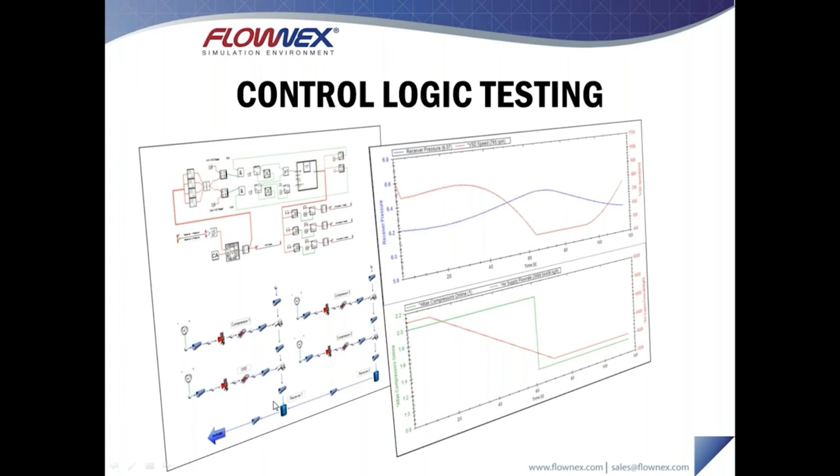This is because the supply into the tank is not equal to the demand out of the tank. This then results in a gradual increase in our variable speed drive, which then begins to make up the difference between the supply and the demand of air from the receiving vessels.